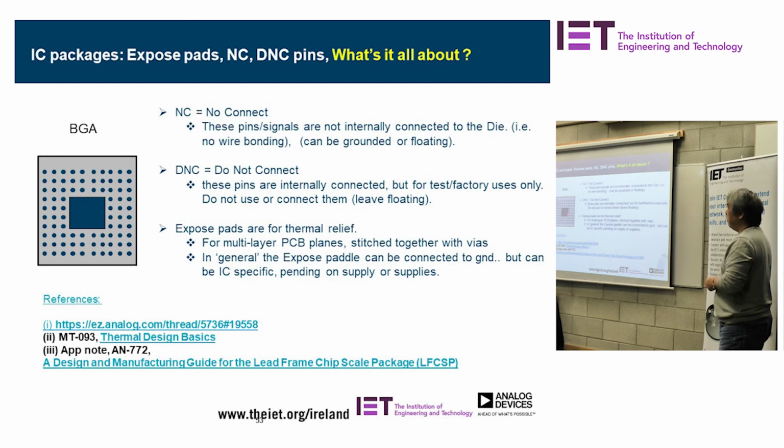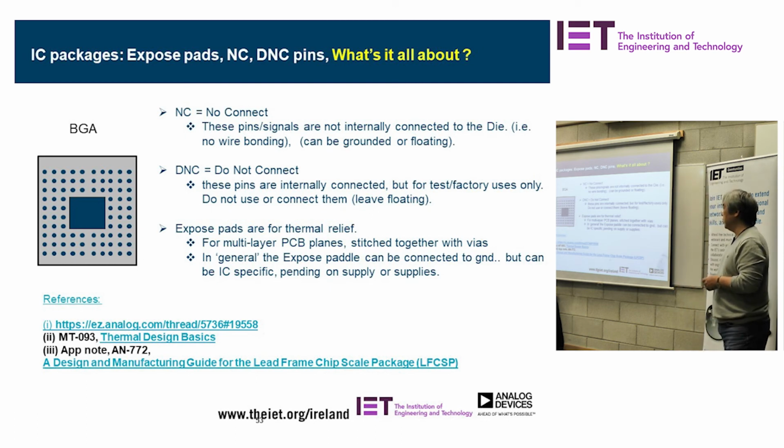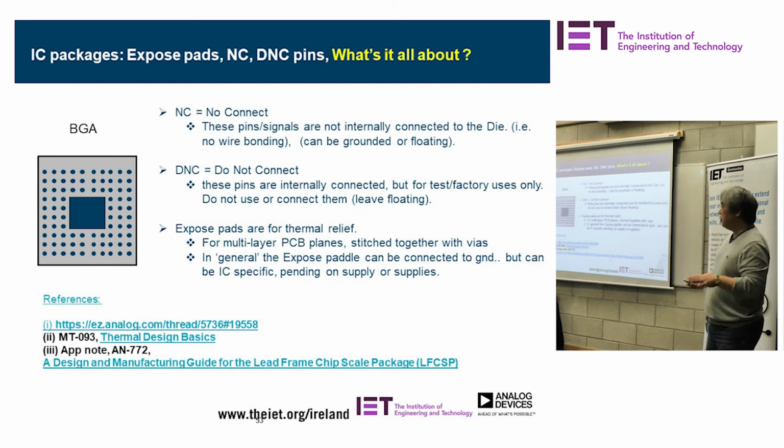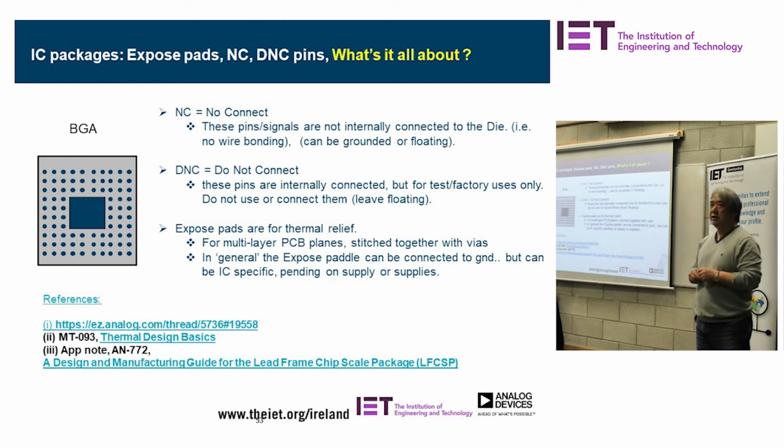Normally they connect to ground, but not always. I've written an article on it to tell people to be aware of it. Don't always connect to ground. Some need to be connected more negative, or maybe more positive. But you need to look at the chip, how it's being done and how it's been connected. So do not assume to connect all of them to ground. In general, yes, but some of them could be very specific.